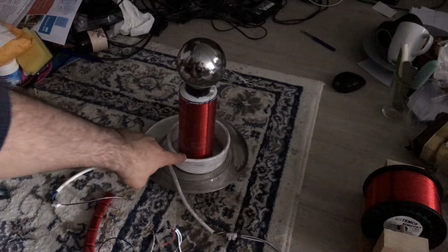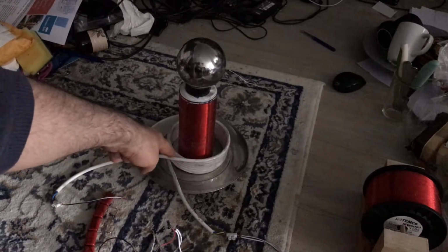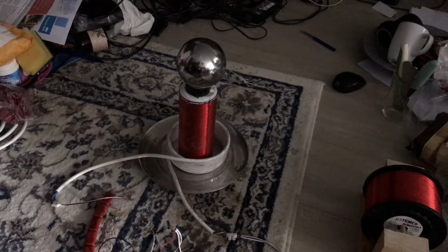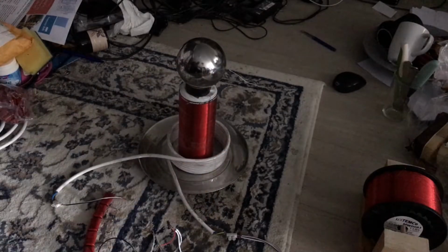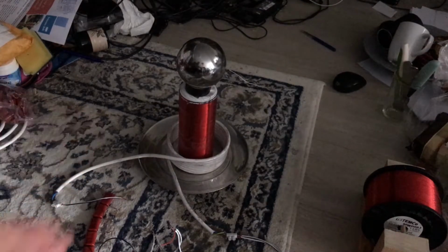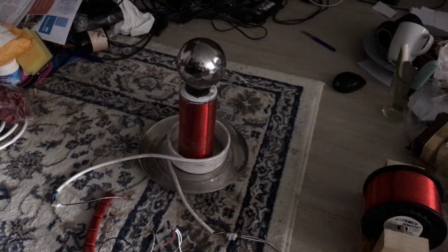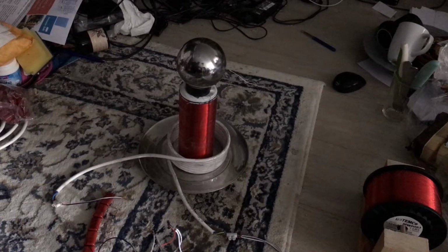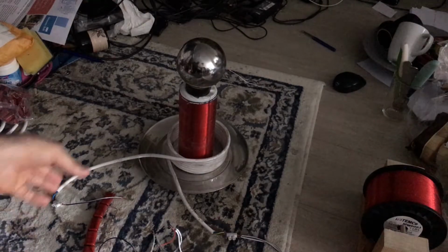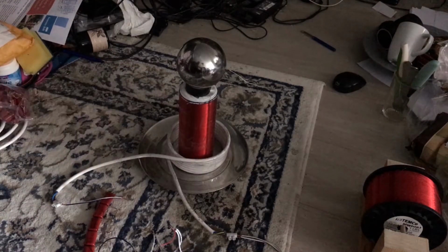In this case, I put the primary coil a little bit close to the secondary coil. And what you observe is that we probably will get discharge from the secondary coil to the primary coil. Obviously, this is not what we want, because those discharges are not useful, and if we have really powerful source, those discharges become so strong that it will burn the secondary coil. So certainly we have to put this secondary coil in the center.